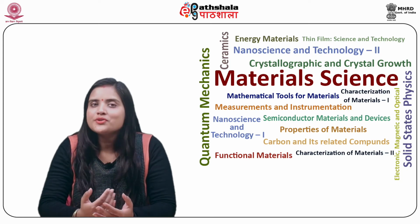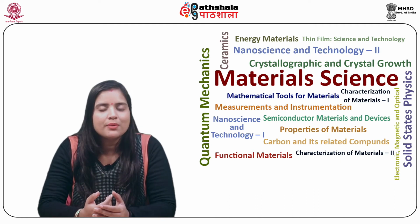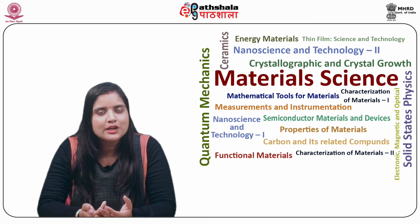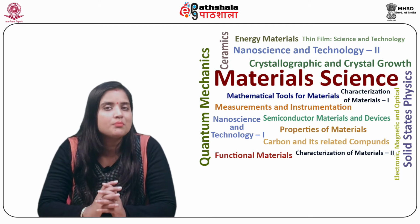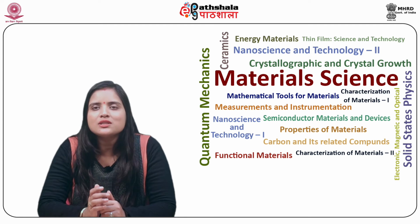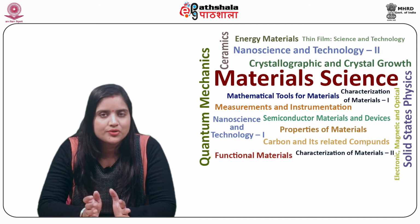The method was devised by Benjamin in the late 1960s when he produced fine uniformly dispersed particles of various oxides such as Al2O3, Y2O3, etc. in nickel-based superalloys which could not be produced by conventional powder metallurgy. This method has revolutionized traditional synthesis techniques which mandated elevated temperature processing.